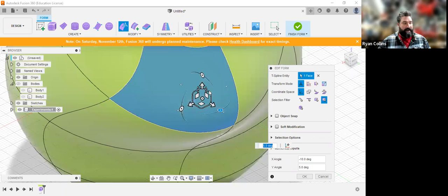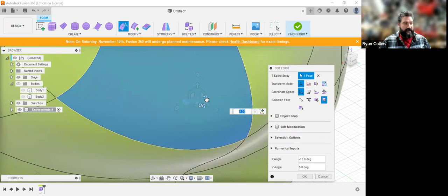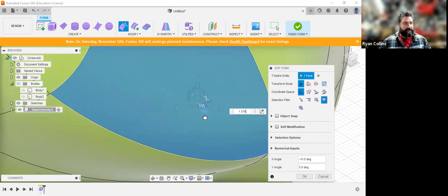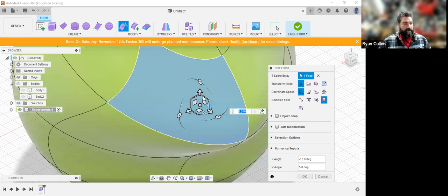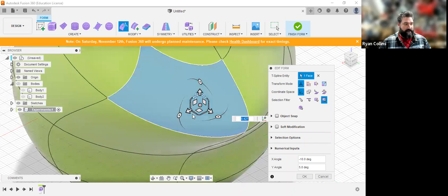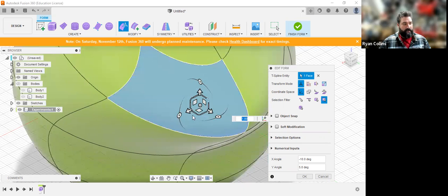What are these arrows out here? These are your scale tools. You can freeform scale stuff up and down. The straight lines are a non-uniform scale outward in the axis direction. So in the Y-axis. Line across, doesn't matter which side. Non-uniform scale in the Z-axis. And you get the idea for the other one. The curve is both X and Z axis in this case, or over here, X and Y.